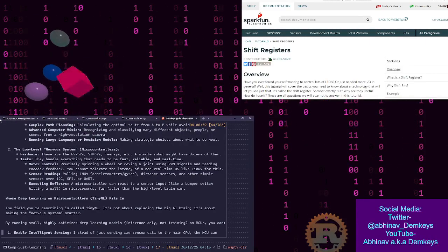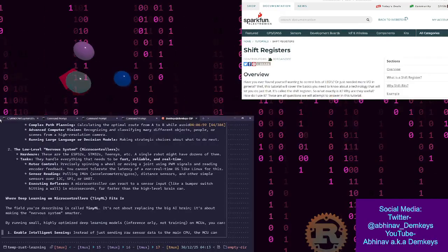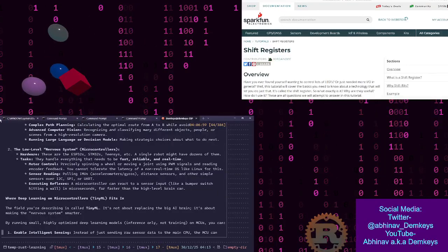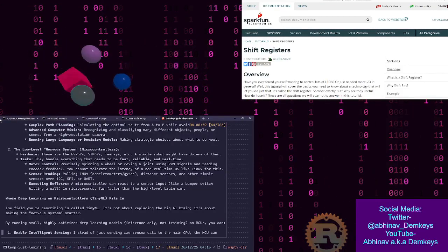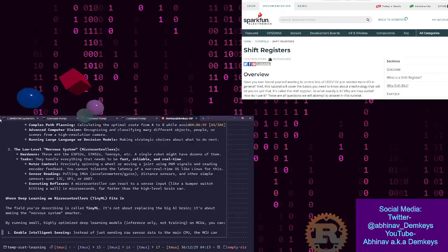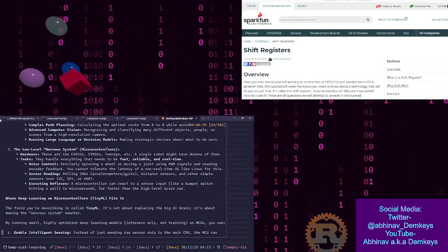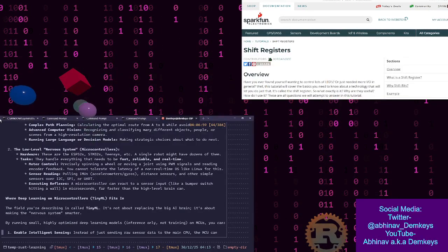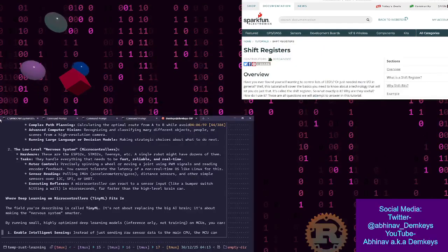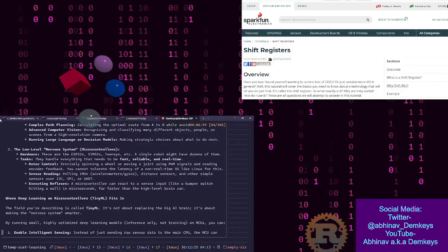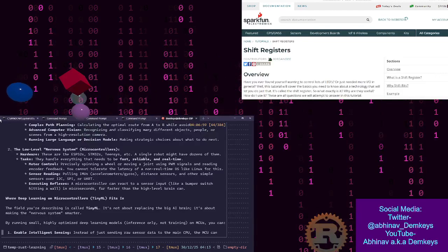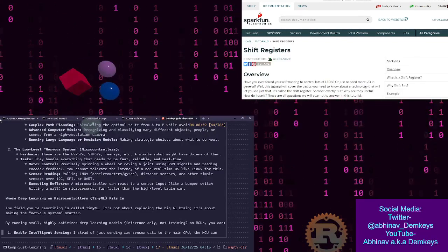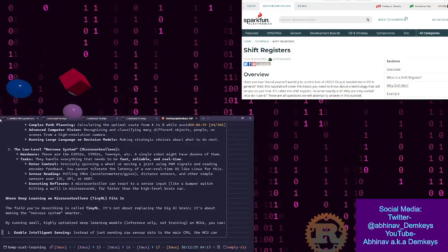Actually, yeah, let me type what is a bumper switch. A bumper switch sensor is a simple physical pressure sensor that detects contact, often used in robotics and industrial automation to prevent collisions or trigger actions when a surface is touched, acting like a momentary switch that closes or opens an electric circuit upon physical impact, signaling a digital pressed state like one or low to controlled systems.